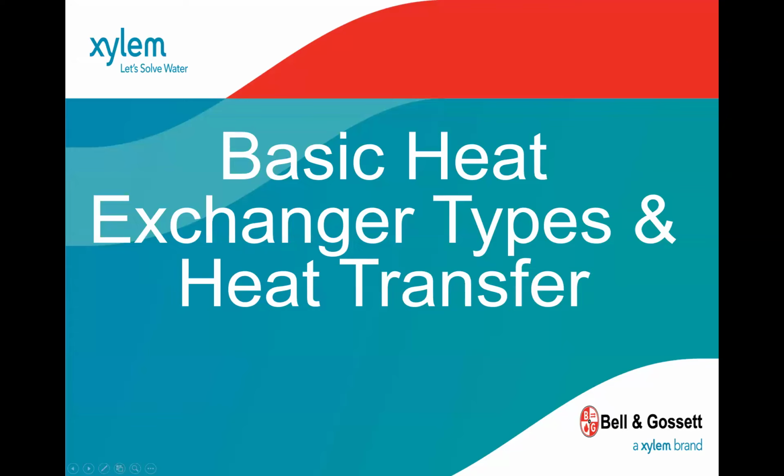So whether you're saying how many BTUs are in this tank that are above 40 degrees, if you were doing a domestic water system and trying to figure out usable volume, you'd be able to say, okay, well, I know that a British thermal unit or BTU is 1 pound by 1 degree. It starts making sense why we take 1 gallon, multiply 1 gallon. We're looking at GPM, we're looking at 1 gallon. 1 gallon weighs 8.34 pounds per gallon. So that's the weight, just for some of the calculations, but making sure that they're equal. And that's the item that's mentioned down below.